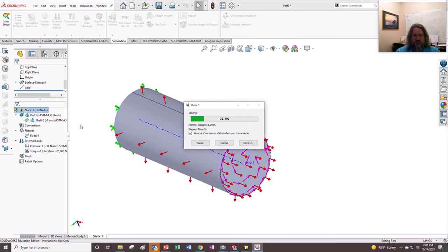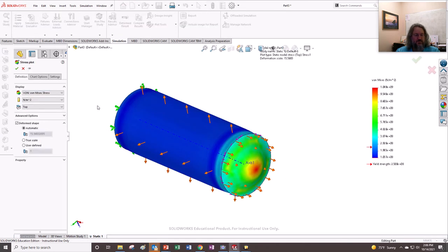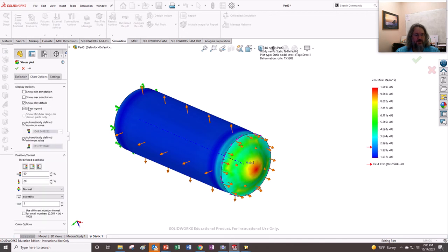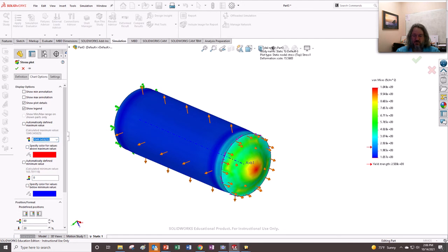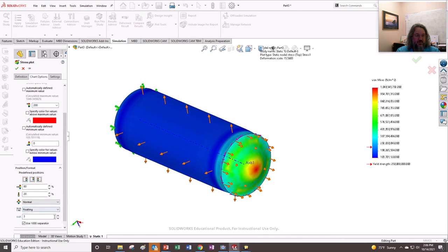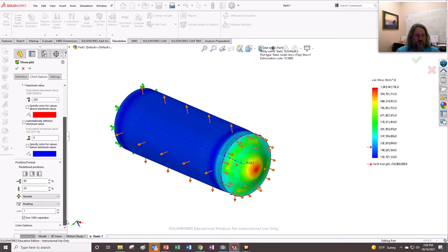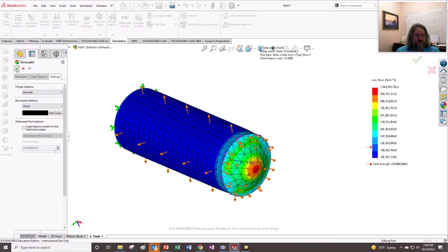And let's get all the same things out here for our results. So in our results, we will change it to megapascals. I will go from 0 to, what did I do down here? 200? Yeah, I did 0 to 200 this time. My previous time I did 0 to 500. And when I ran it before we were here together, like floating, we'll get down to only one decimal place, and we'll make it discrete, and we'll show the mesh. Boom.